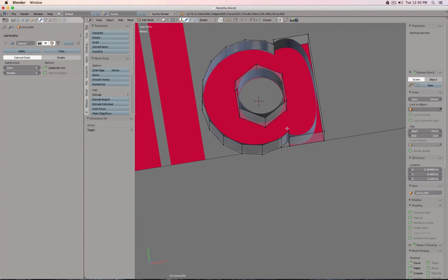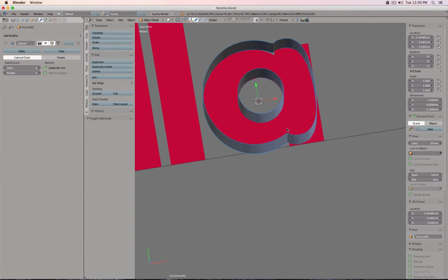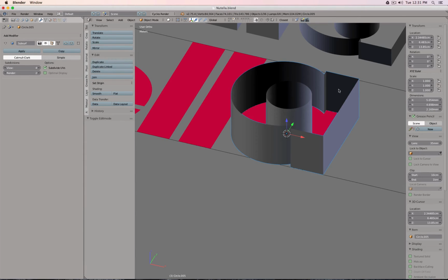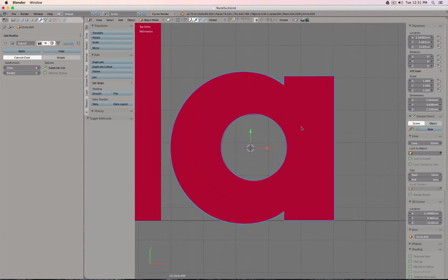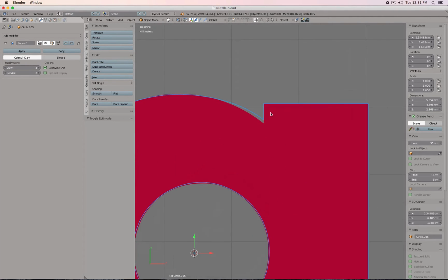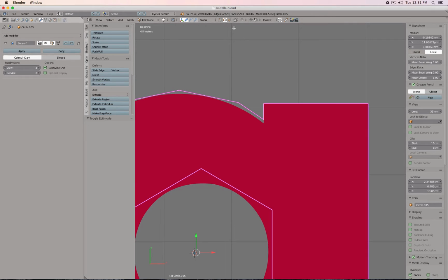And let's take a look. It looks terrible because it's all too soft. So now I can go back and select all these outer loops, and then, for example, here those sharp vertical edges to be sharpened, and then either punch in 1 for crease or Shift E, 1, enter. Let's go to top view, and wow, this is actually perfect, a nearly perfect match, or very close. I wouldn't say perfect, but if we do a rendering, that is totally fine.